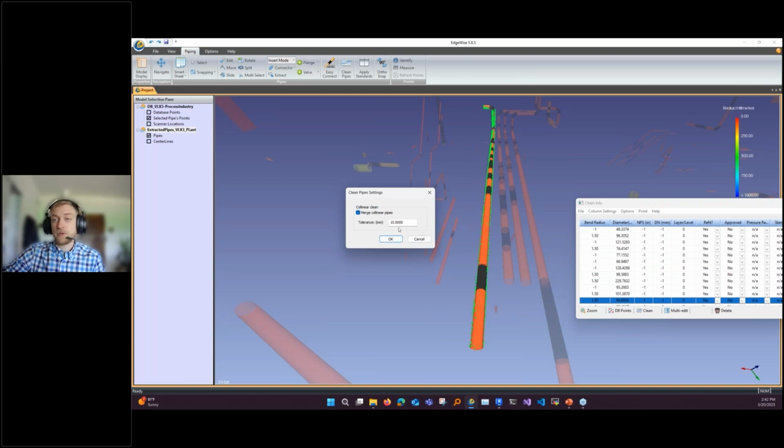The default workflow keeps as-built conditions. So we will keep bends and bows if you leave it at the 10 millimeter default value, or the inch equivalent. That effectively is trying to straighten things out when it can. It just says, if it can't be straightened out, like if it's too far off of the point cloud if we make it a straight line, then don't do it. It's kind of the way to think about it.